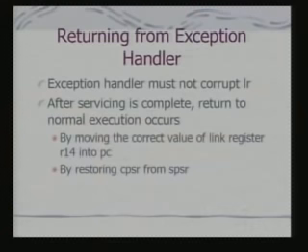So, how do you return from an exception handler? It can be using any instruction for that matter which will restore your PC to the corrected value of the link register. And what is important is that the exception handler must prevent corruption of the link register value which gets loaded when the mode switch takes place. This is very, very important.